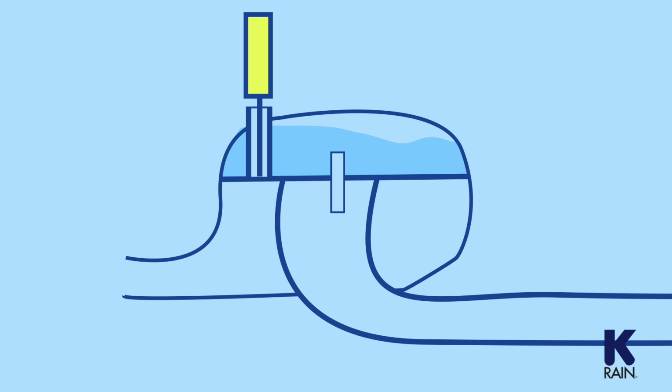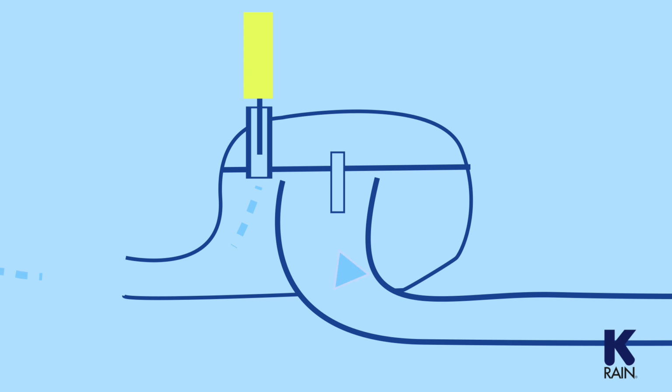The valve opens when the solenoid energizes. The plunger lifts and unseats from the exhaust port, allowing water to flow out of the chamber above the diaphragm, downstream to the zone line. There will still be water flowing into the chamber through the metering system, but water will flow more quickly out of the exhaust port. This eases the pressure on top of the diaphragm, which is then overcome by the water pressure coming in from the main line. Water from the main line then forces the diaphragm open, and water flows out to the zone.